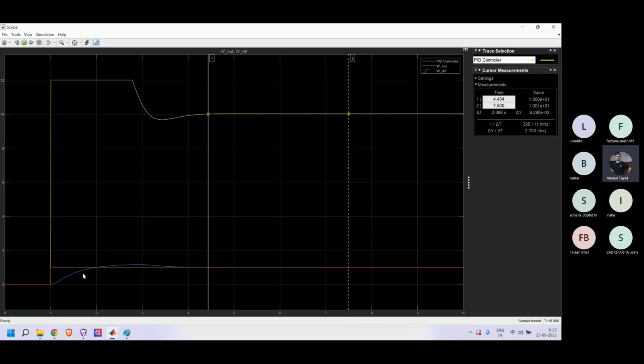So either you have to change the motor itself, because the motor parameters certainly don't seem to support 2 radians per second with 12 volts of saturation voltage, right? So either you'll have to change the battery or the motor to achieve 2 radians per second actually.